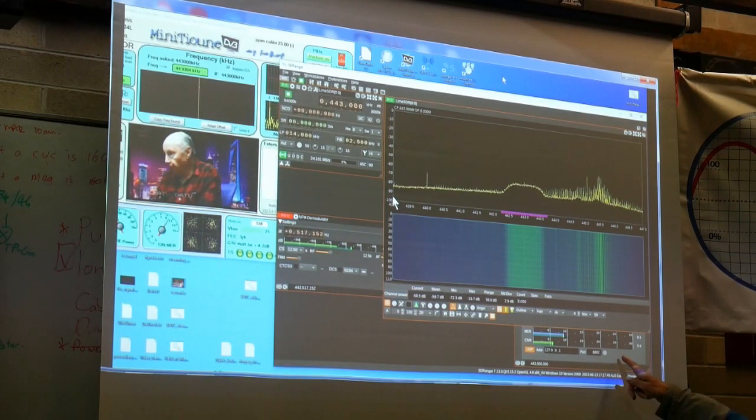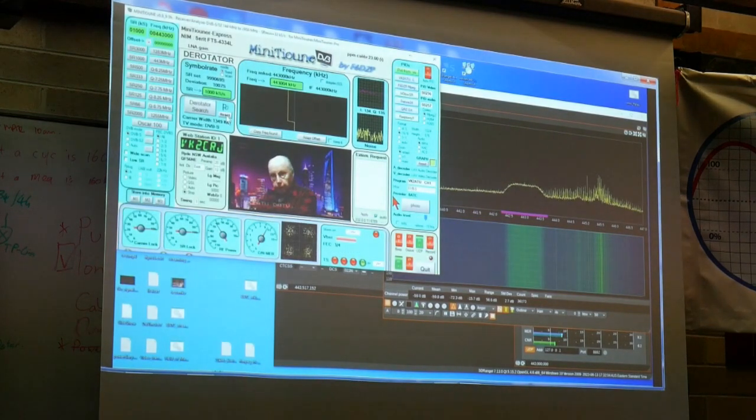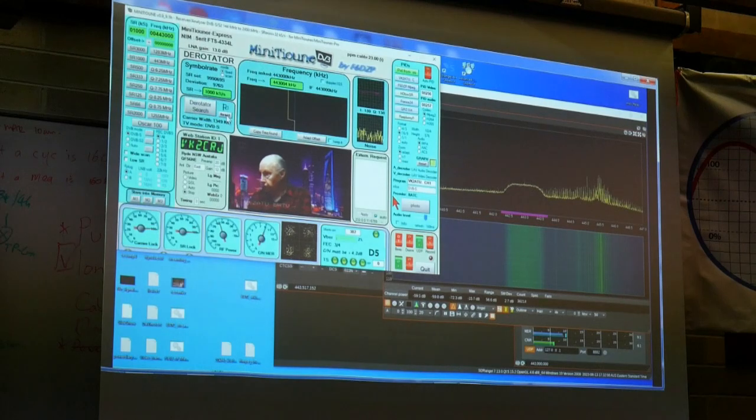But you can send a UDP stream out from the SDR Angel software, so that's the better way of doing it. Actually, I've found when you try and use the internal viewer, quite often it stalls. But you can get the UDP stream out of it, then you can send that off to something like FFplay, and you can watch the pictures on that. Works a bit better.